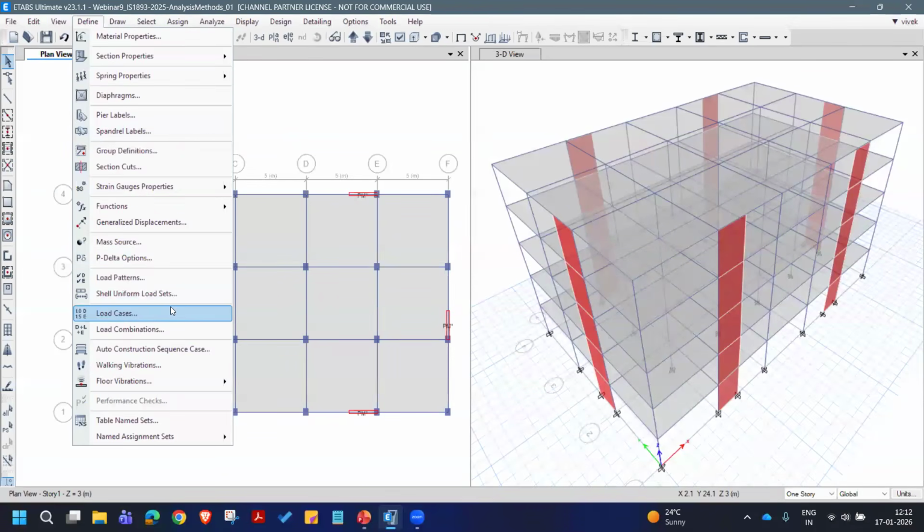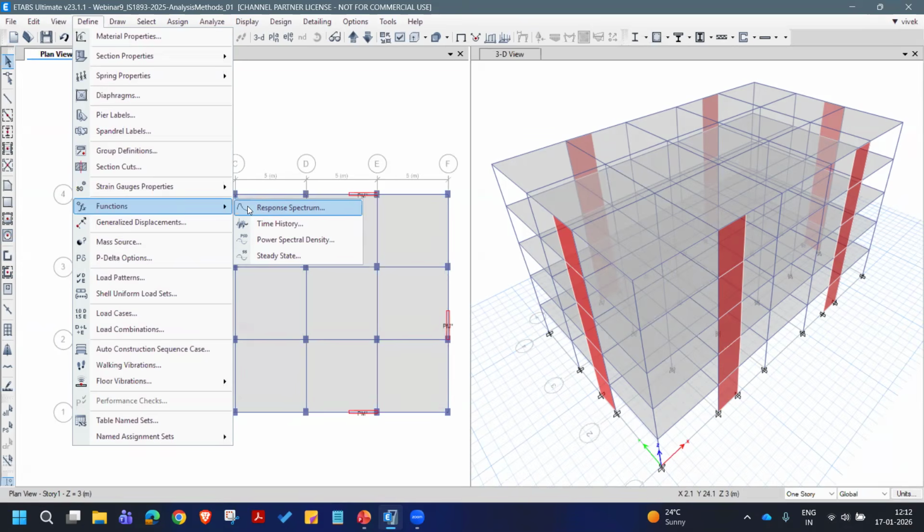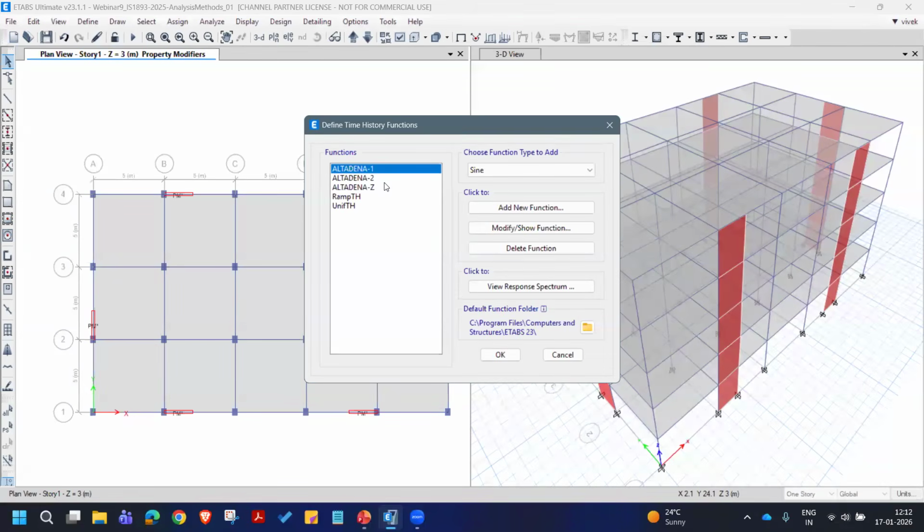Next, we can use this the time history functions directly in a time history load case. However, there is a scaling is always required based on the region or the site spectra or the design spectra, which is usually done, which is also available in the program as an additional tool, which I'm going to use because these are unscaled recorded seismograph data.